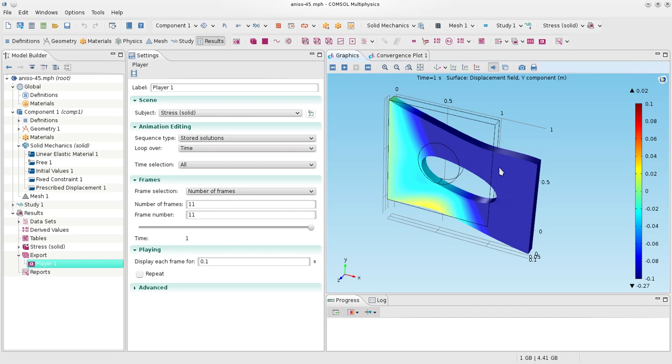So, of course, the length does change, but it's just trying to stiffen that direction so that the length doesn't want to change that much. So it forces the plate to move down. So I just impose a normal deformation, but it also moves as if I have sheared the plate, but I haven't. I haven't applied any force along the minus y direction. So if this were an isotropic material, you would have immediately said you pulled and you pushed down. But presently, I'm only pulling, not pushing. Still, it moves down due to normal shear coupling. So that's what normal shear coupling means.